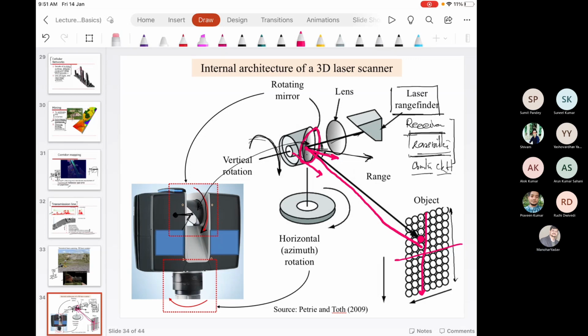Okay, fine. Now, if you initialize this LiDAR system, with respect to the rotation, again and again on the same line the laser beams are fired, and the same points' coordinates are calculated again and again. But our aim is to cover the entire area in the surrounding of this laser scanner unit. What should be done? Again, you need to provide a horizontal rotation.